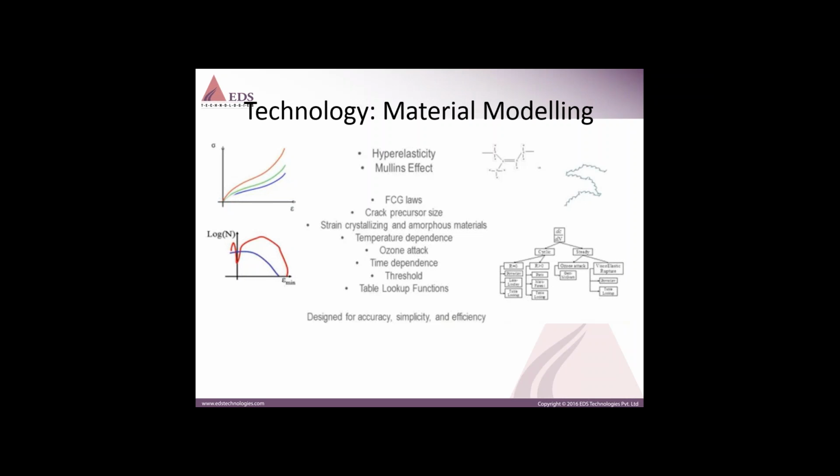Using these material models, the temperature dependence of the material can also be studied. Even time or environment dependent factors can also be included. There is also a lookup table which is available for the strain crystallization method, which will let you accommodate very accurate crystallization effects in the analysis.